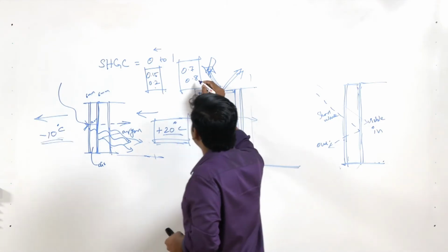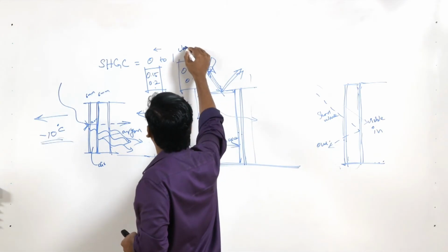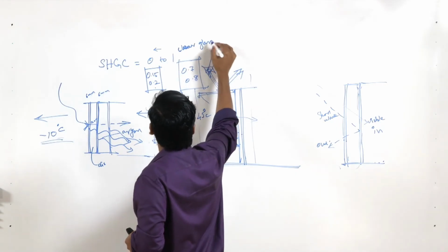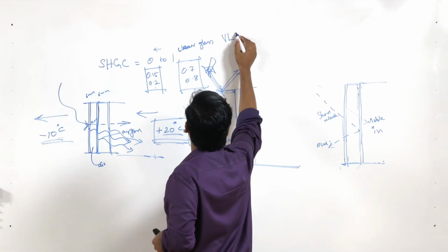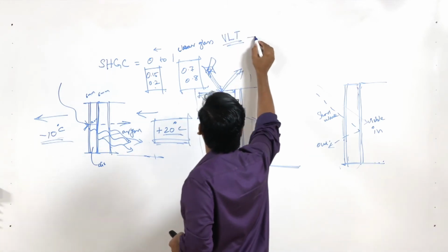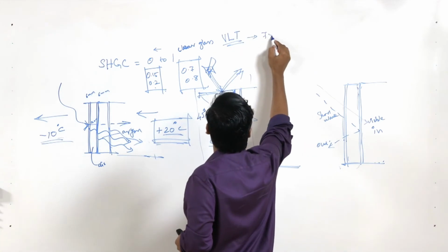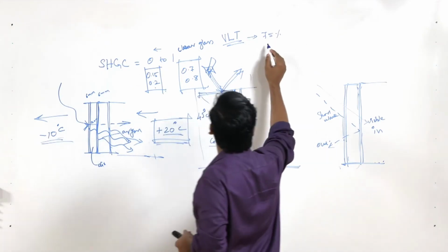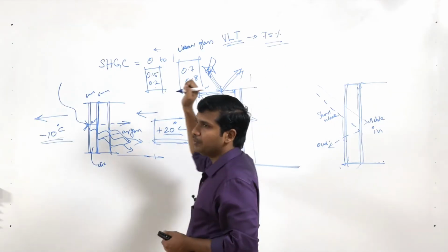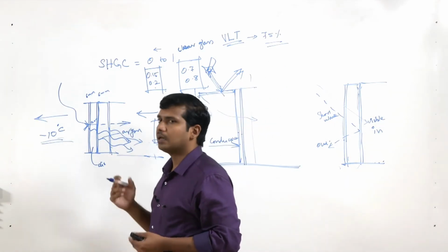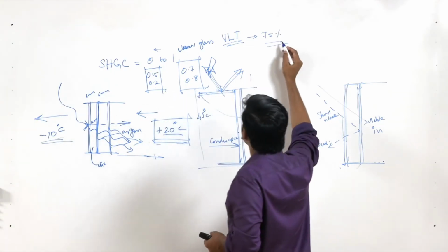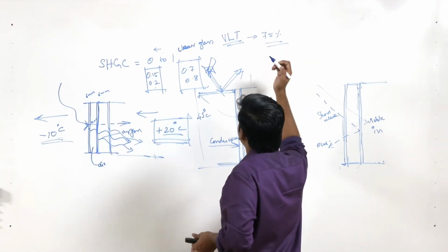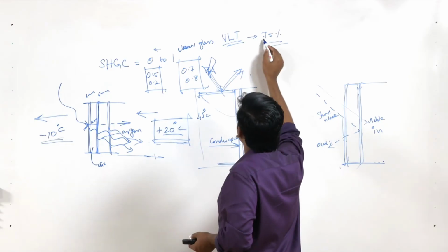Say when I said 0.7 or 0.8 for a clear glass, the light transmittance or visible light transmittance, that is VLT, here will be around 75%, that is 75% of light is transmitted into the building, which will actually help you in reducing your lighting energy or lighting loads. So the number of lights can be less, or fewer lights can be turned on,